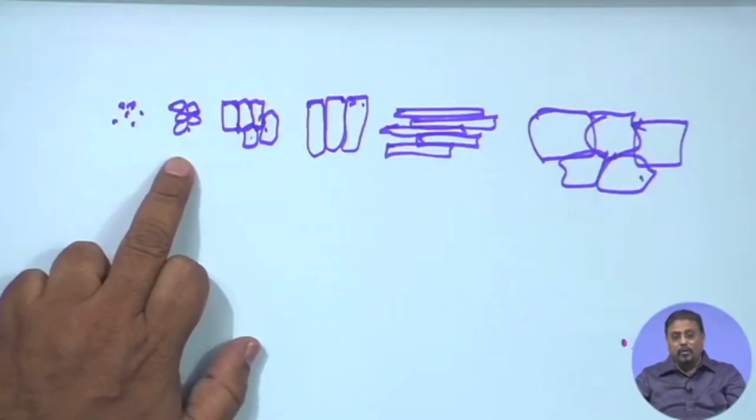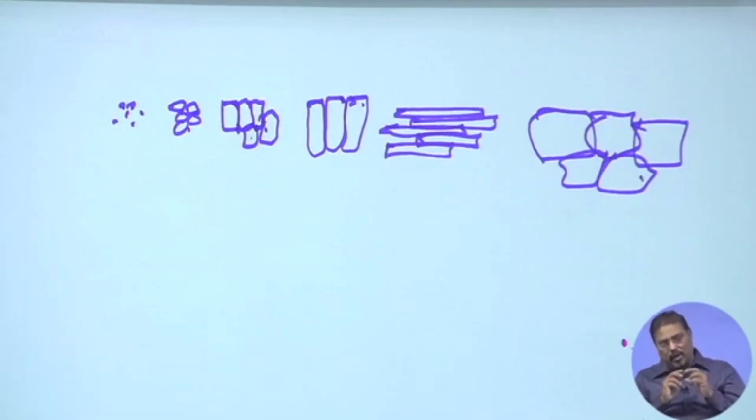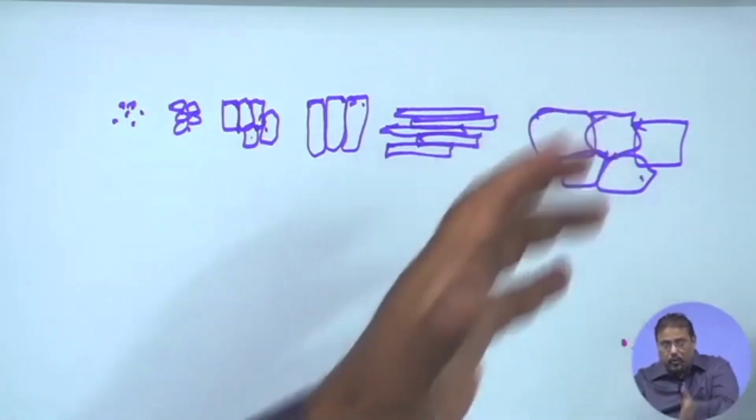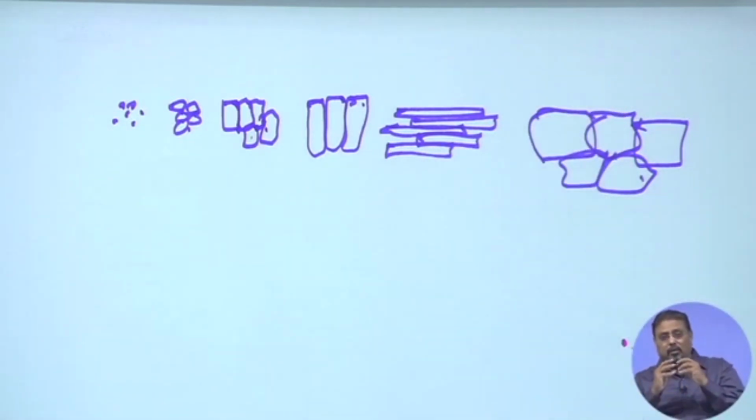And then if you find it is not that dusty, but still there is a layer of dust, then you should understand there is a granular structure, but at the top surface, because of the wind erosion, the granules have been further broken, and they become small fine granular, and the top layers are flowing out, but overall it does not look very dusty. When you look at the blocky one, if you take, say, 1 foot by 1 foot by 1 foot, one cubic foot of soil, you will find that the sizes are not very large, and they are almost cuboid kind of things.